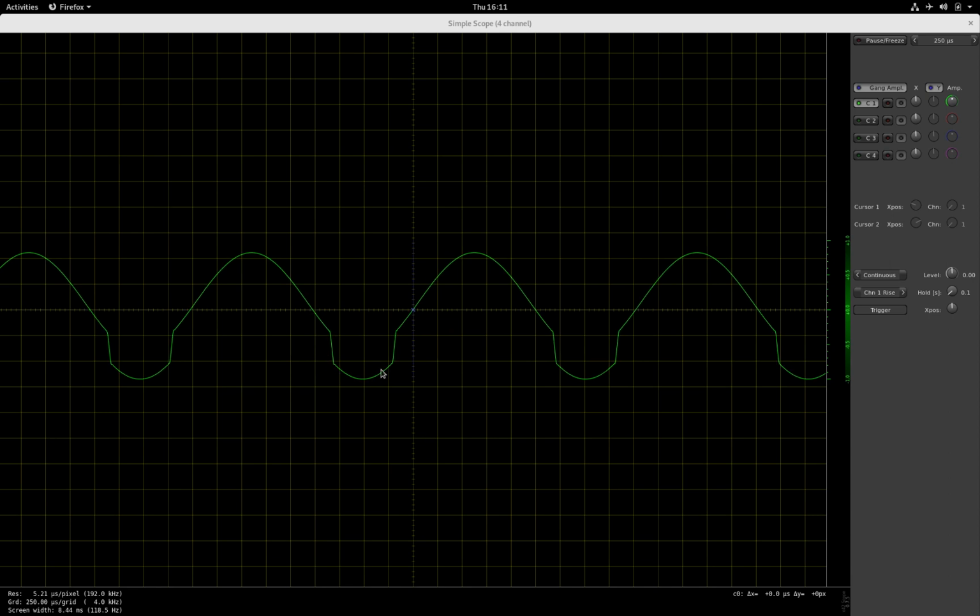If the input amplitude to the fuzz is reduced, the bias voltage moves downwards along with it, so that this nonlinear region moves closer to the zero line as the amplitude of the input signal is reduced. And therefore the input signal will always cross through this nonlinear region. I will now demonstrate this to you by reducing the output amplitude of the signal generator.